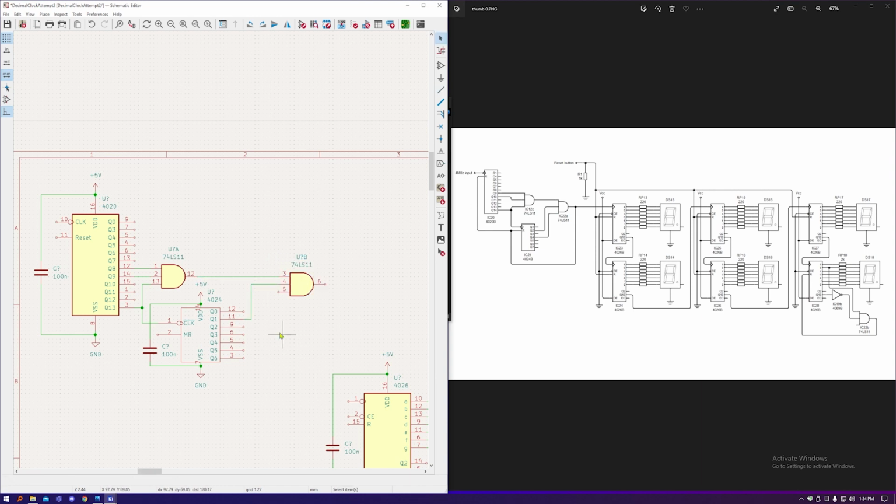If you're on the Formula Student team, I do have quite high standards for layout in terms of neatness and things. So, for example, these two wires that go to these pins, it would be frowned upon if they were done like this, so they crossed over. Complexity is fine, but unnecessary complexity is not good.